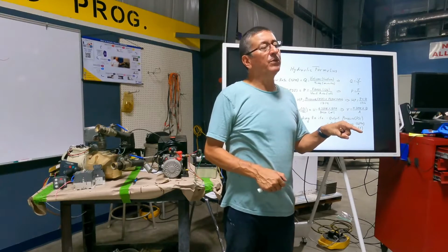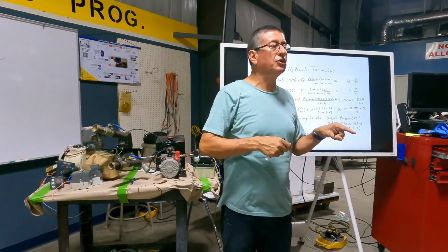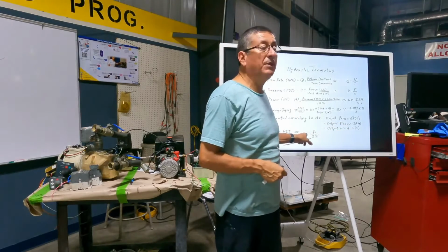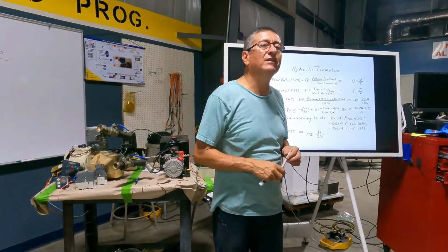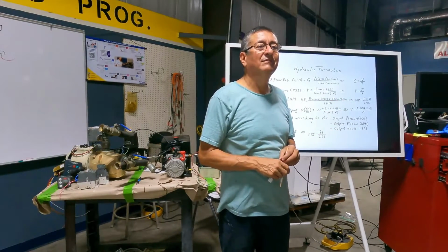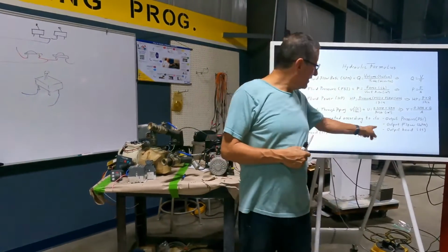This pump, the output pressure is 60 psi. With 60 psi, how much distance do I reach? Okay, the distance is equal to the psi times 2.31. It's 130 something feet, yeah? So 130 something, yeah, 138. Nice, no? That formula is magic.